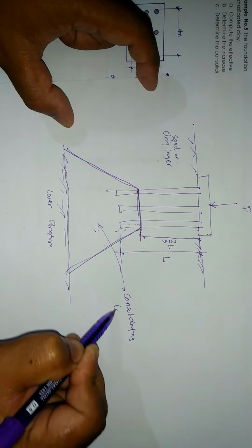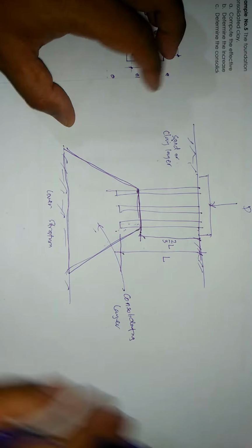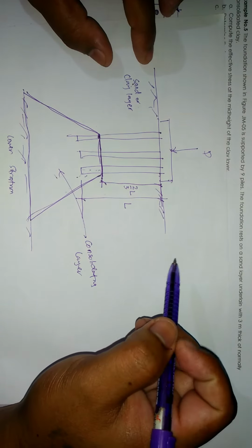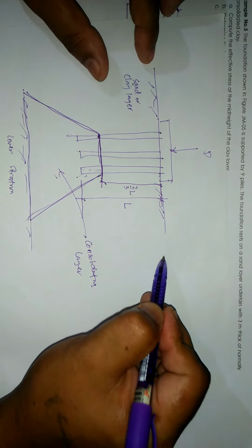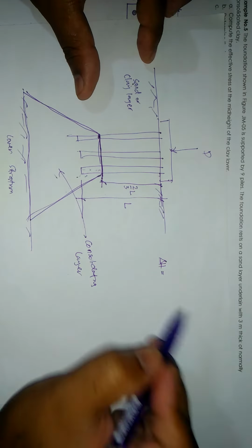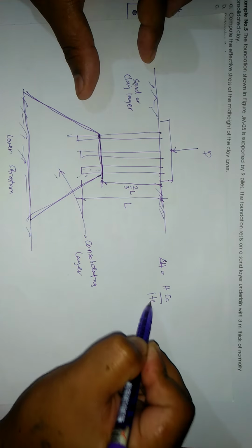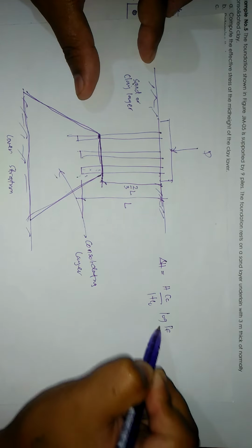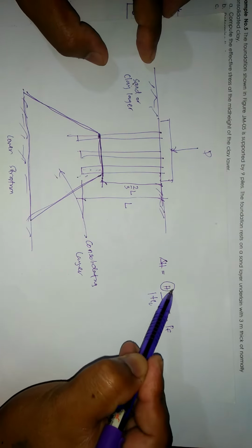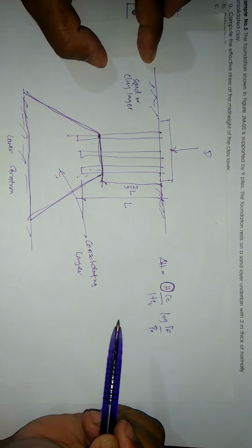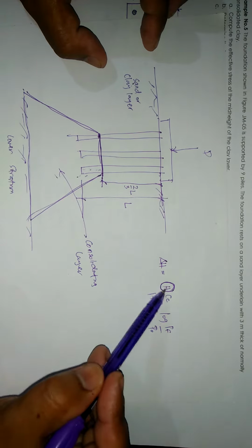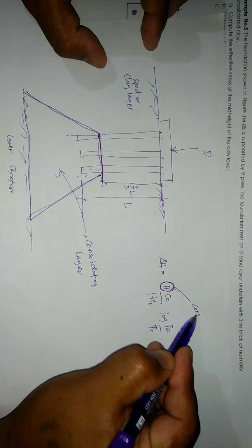So, what is the purpose, sir? Bakit mo pinakita yan? Kasi dun sa formula natin sa normally consolidated and overconsolidated soil layer, di ba, sa normally consolidated settlement, delta H equals H Cc over 1 plus e, logarithm of P sub f over P sub o. Kasi dito kung minsan, dito kayo magkakamali, yung value ng H. Like what I've said, if it is a pile group yung given, ang H mo dito would be your consolidating layer.